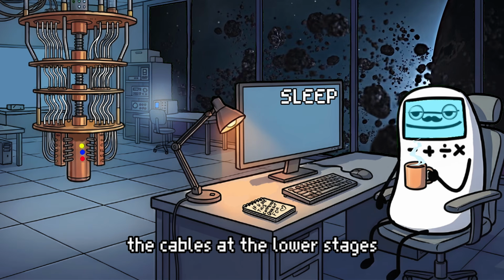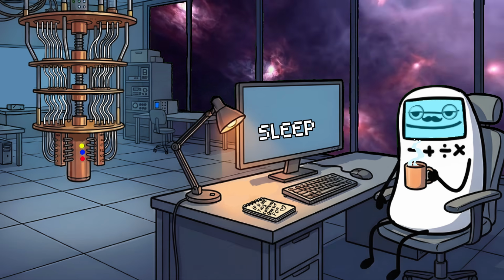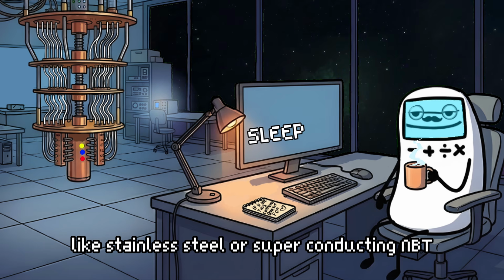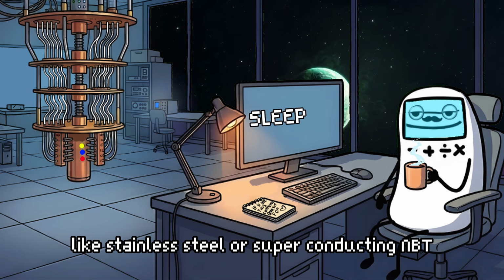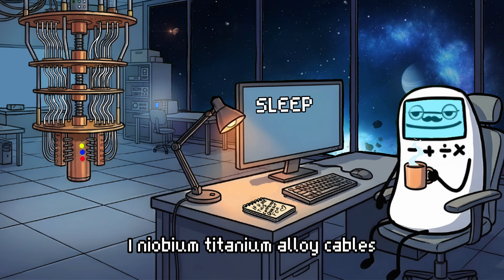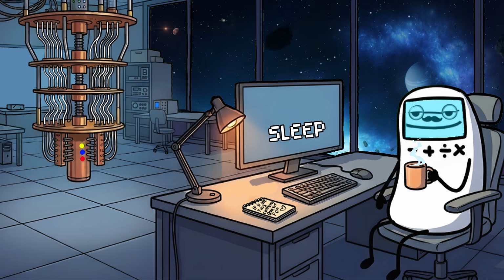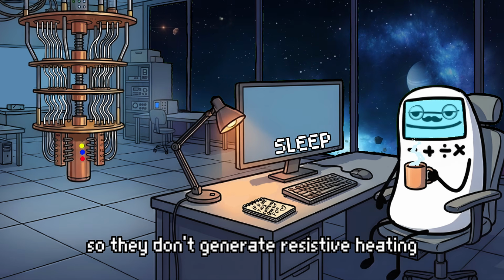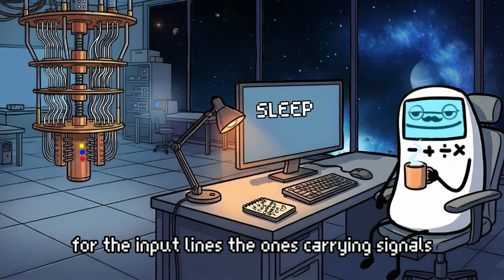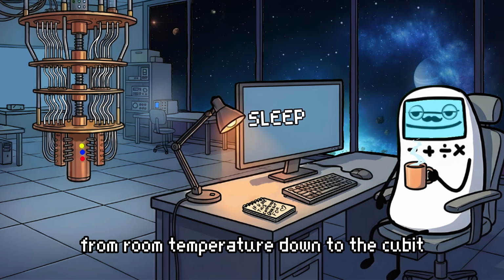The cables at the lower stages are made of materials with very low thermal conductivity, like stainless steel or superconducting NbTi (niobium titanium alloy) cables, which have essentially no electrical resistance, so they don't generate resistive heating, and which have low thermal conductivity.